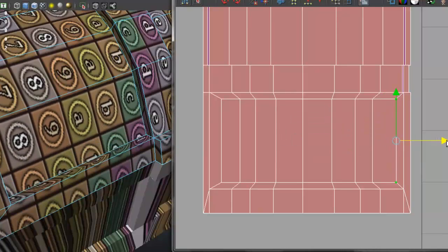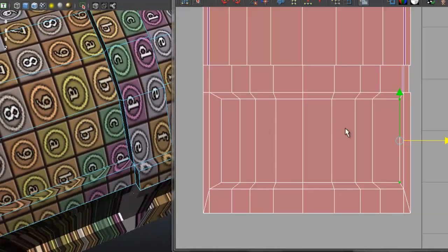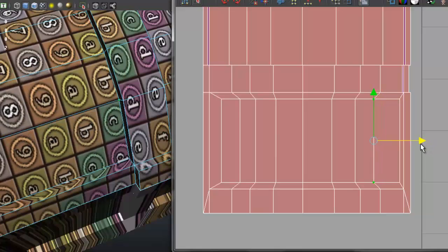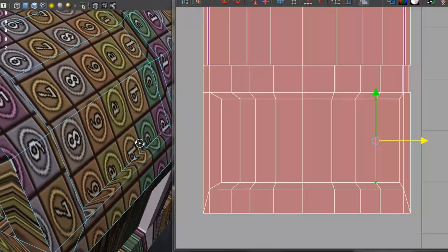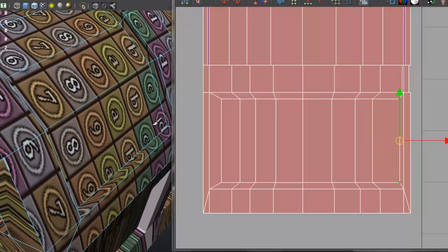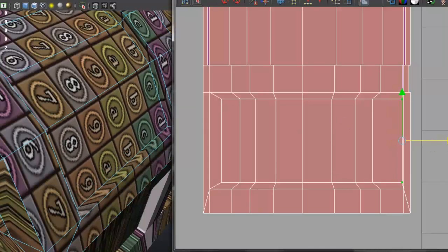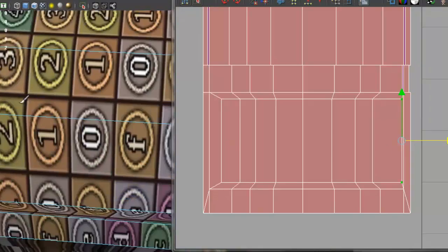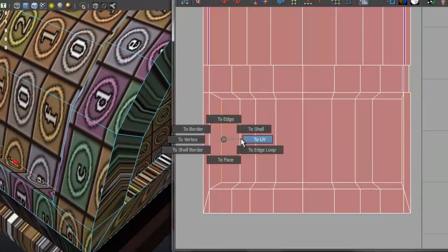And I just want to move this one, maybe I can make this look more like squares for that part. We want the texture to look more like squares, and sometimes you can do it that way, just selecting one edge and going into UV mode and moving that edge until you see that it looks more or less like a square. And that means there's going to be less distortion for our texture in that area. I'm going to do the same thing with the other side.